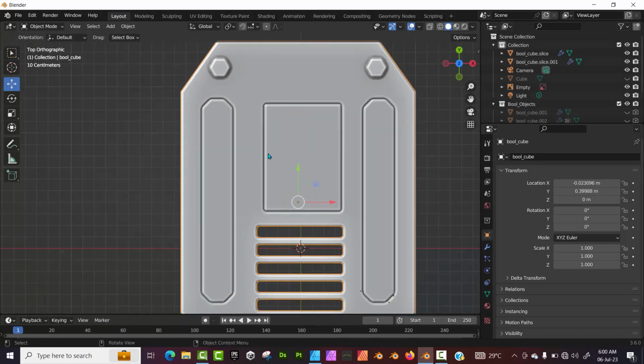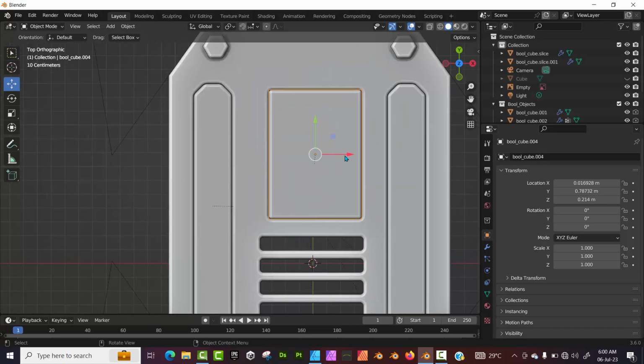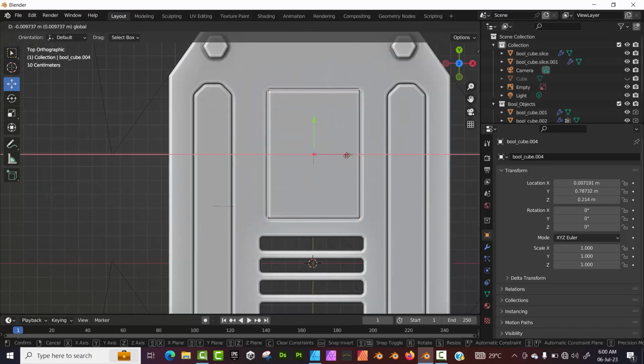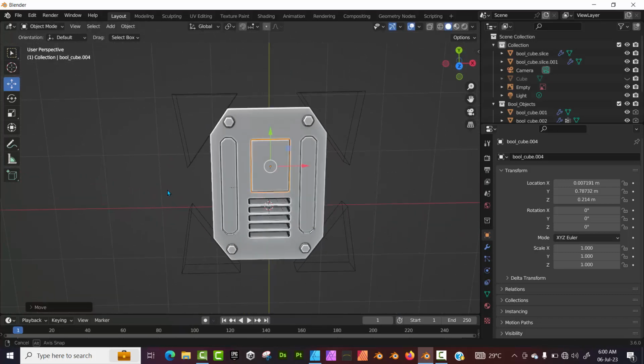Now it's a bit tilted towards the left, so let's edit that. So let's click this, press F, show booleans, click on this boolean object, and we could just quickly drag this to slightly arrange this. So this time around, we don't even need to jump into the edit tool, and voila, we just have that.